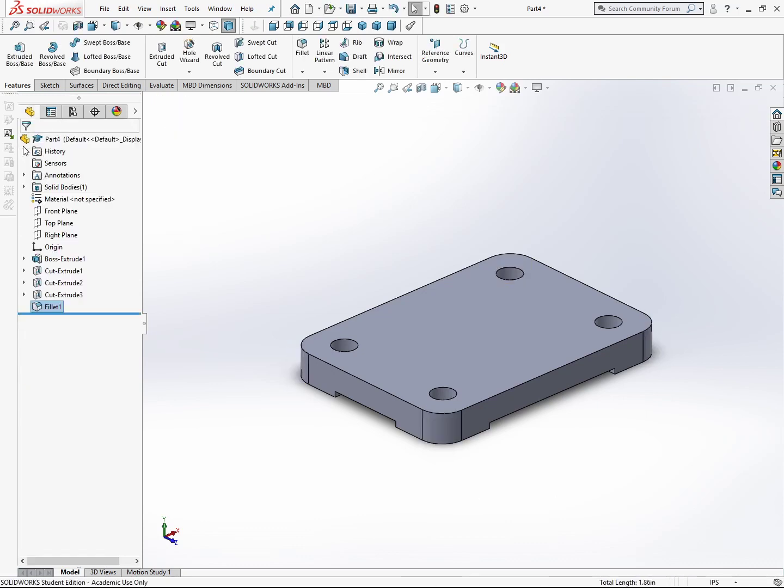Usually it is a good habit to create fillets as the very last step. I just do it here to finish the lower part of the plate, and it has no bad influence on the next steps. So now the plate is finished and we move on to the angled part. Here we have to create 2 references to obtain the fixing point I showed in the beginning.